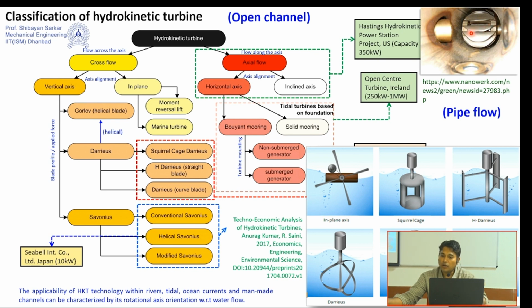If there are more blades and I wish to install it within the pipeline, then I have to modify the blade. Instead of a rectangle, I have to modify the blade in this manner so that it will have a spherical shape here. Then it will be able to rotate inside this cylindrical domain.